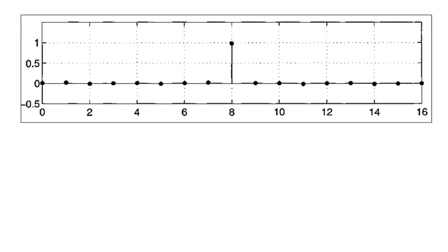Now after the training sequence, the equalizer will not have any knowledge of the desired signal d of n to be received correctly at the destination, and it has to rely on decision directed adaptation to generate the error sequence to drive the coefficient update equation that we have mathematically shown here. Now let us visualize a received sequence x of n, denoted in the mathematical relations, and this is for example the first 100 values after the training period here.